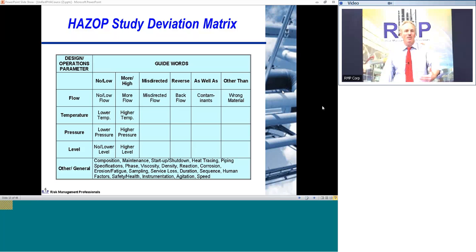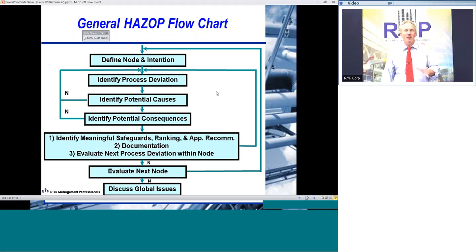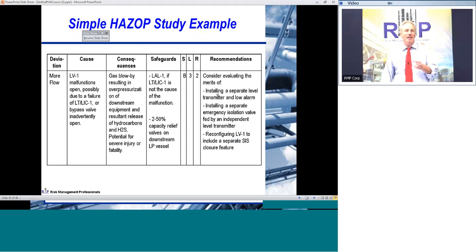You're doing that in a very systematic way, applying those guide words and parameters to pull together the scenario and really understand what can go wrong, how bad is it, risk rank it, and then conclude, are there weaknesses or not. And in a lot of cases, if you don't have information or you're at the borderline and the team's not sure if it's safe or not, you might selectively apply a tool like a LOPA or something else for specific scenarios where you need more information.